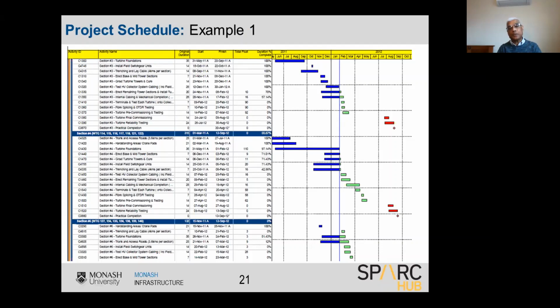There are layouts and filters in the Primavera software, so you can use the layouts and the filters to look at the progress of the work or the financial progress of the work, on a cost center basis or a work basis, and then compare and contrast, monitor and control. So it's very important to classify, identify, and then code and document the work breakdown structures at the very beginning.